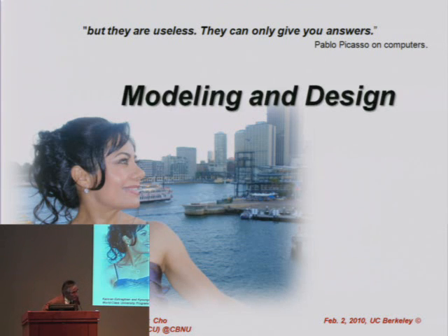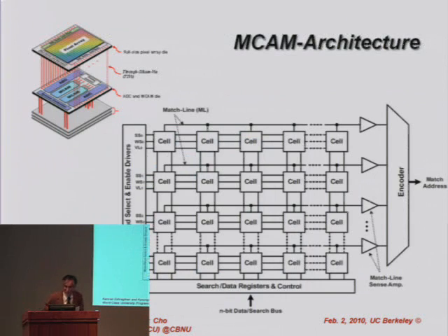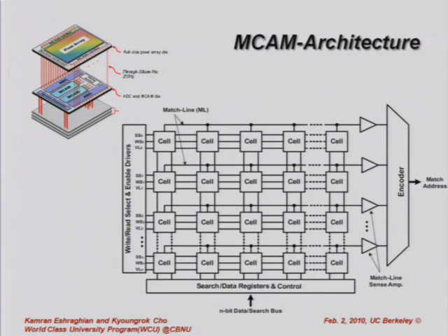In terms of system-on-system architectures, I'm going to talk about a CMOS and Memristor mixed-up circuit through the CAM, content addressable memory, design. Now we are focusing on image mappings. Images from CIS are compared with other images stored in a database. CAM, content addressable memory, is a very suitable search engine to find data in our memories.